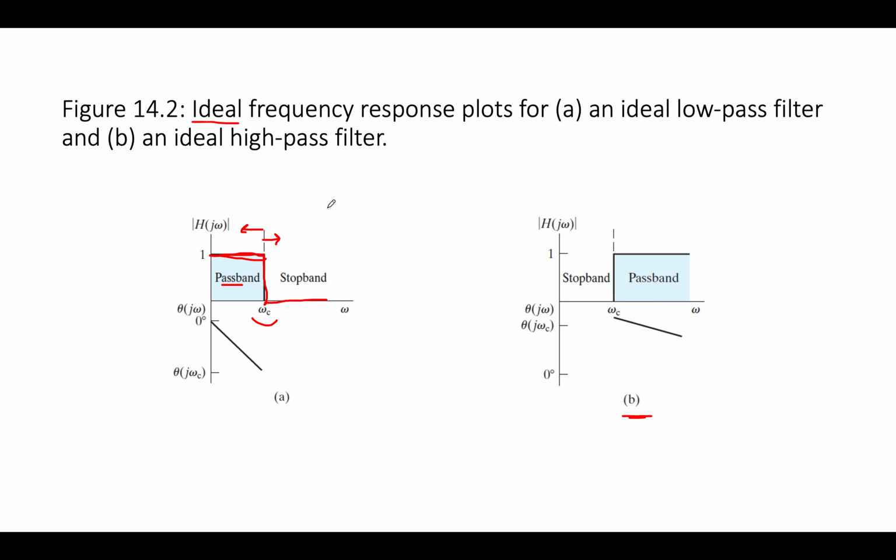Low pass filters are often used to filter out higher frequency noise. Sometimes high frequency doesn't mean very high. Sometimes it can mean something like 60 hertz, if you've got a lot of 60 hertz noise and above. Other times it can be electronic noise or environmental noise or other kinds of signal noise that appear on your signal that is not relevant to the physical problem or to the transmission of the information. So you want to cut off the higher frequencies. A high pass filter is often used if you have problems with low frequency drift or very low frequency signals superimposed on your signal.